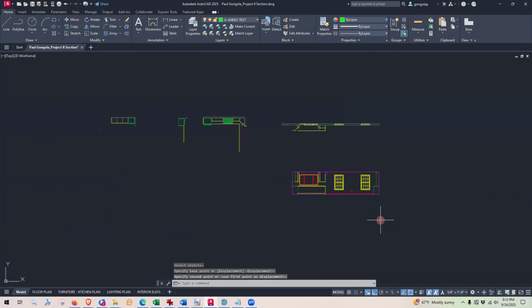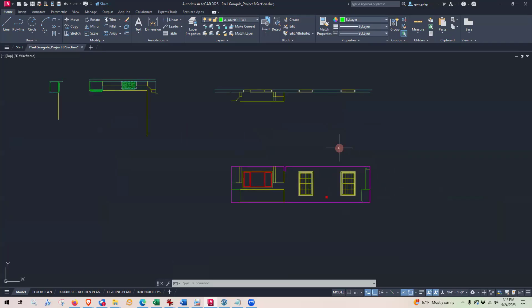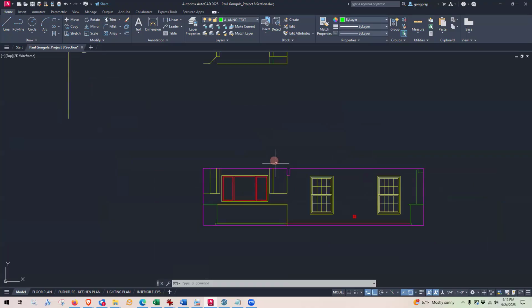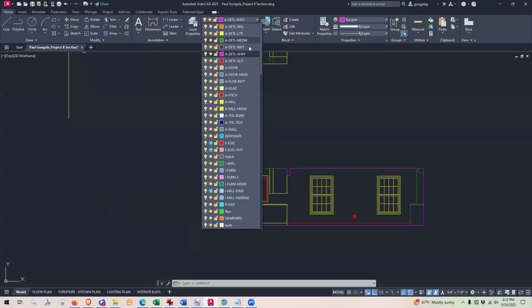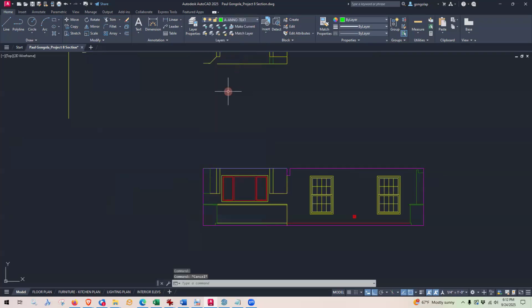So now, last week, when we were doing the elevations and we were looking at the line weights, I was not happy. I just thought that maybe the line weights were a little bit heavy, and then we started tweaking within the viewport to make them lighter. Let's see, I made these lines extra heavy, and I'm going to change that. I'm going to make them just plain old heavy, I think, instead of extra heavy, a detail heavy. I think that is just going to read a little bit better.